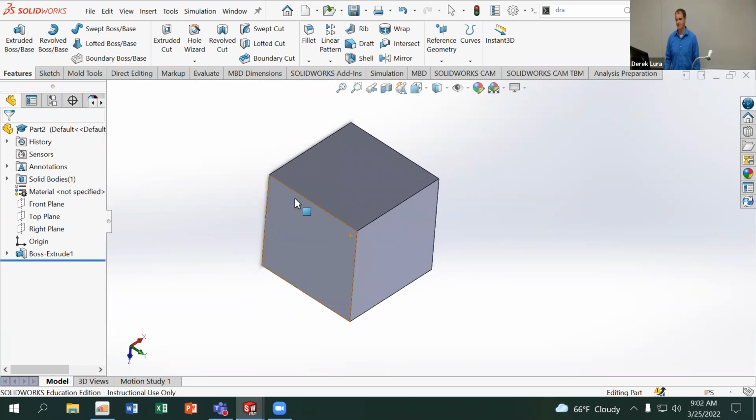So as long as I can specify the direction of pull, I don't have to be quite so planar as I was in the previous example, where everything was on a flat plane pulling apart. So if you're starting with a part that's not very obviously, hey, I can draft this and pull it apart, you can choose the direction of pull such that you are able to manipulate that.